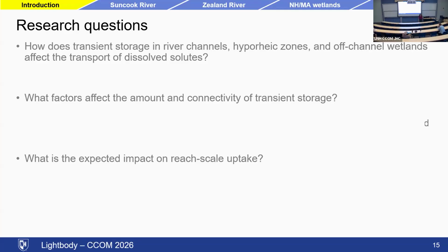You can measure a baseline. So you could measure a molecular diffusion coefficient by looking at it in a microscope, but that is going to be dwarfed. It's going to be overwhelmed by the fact that there is shear within a river, that the top of a river is moving much faster than the bottom of the river. That is going to rapidly spread out a tracer cloud, way faster than Brownian motion.